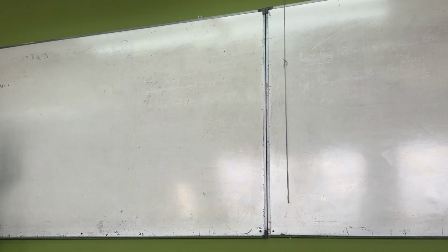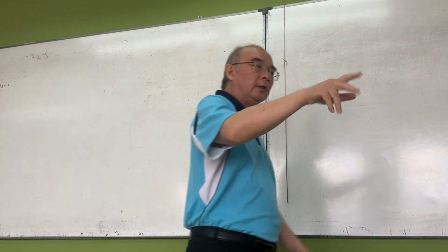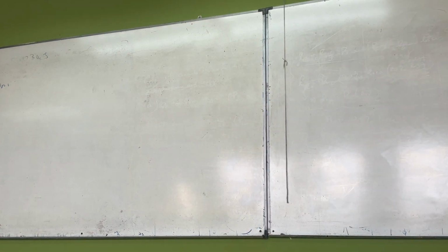Now, before I go on, in the pre-stressed concrete problem, the moment that we are dealing with is a service load moment. That means the load factor is 1.0. Don't use 1.4, 1.6. Understand?